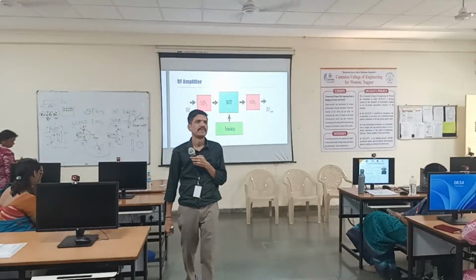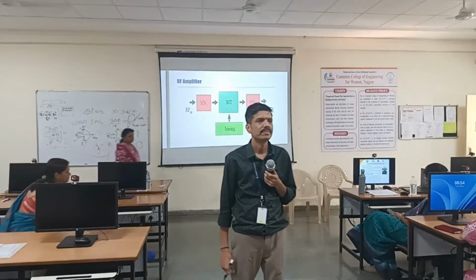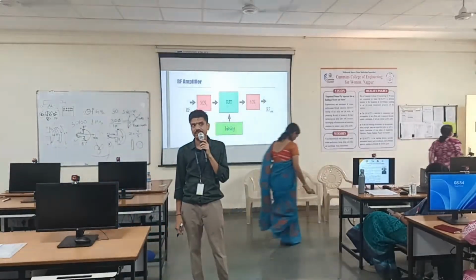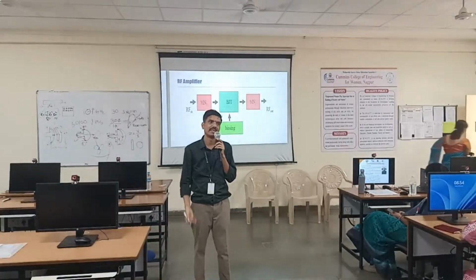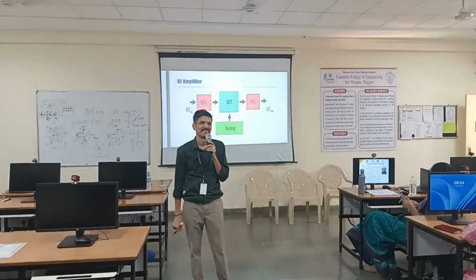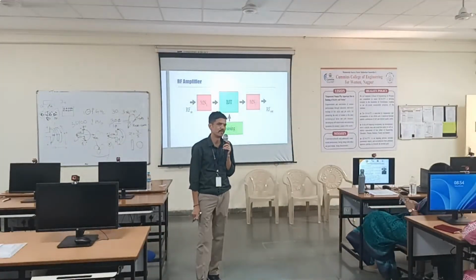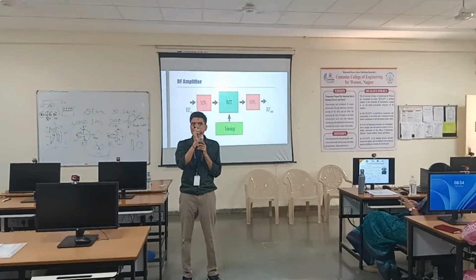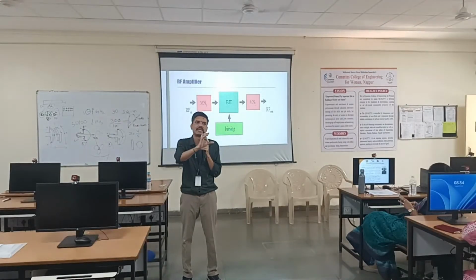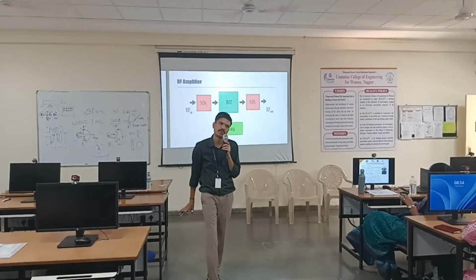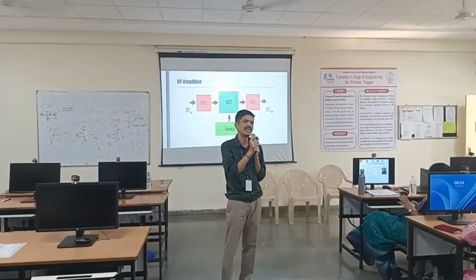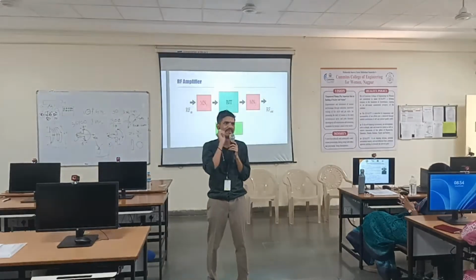Yeah, please. What you said about the width of that line? See, length is independent of impedance. Width is nothing but impedance. Good question. Let's say your length is 10 centimeters. If you change the length to 11 centimeters or 9 centimeters, that line is going to give you 50 ohms only. So you have correctly pointed out the design parameter.